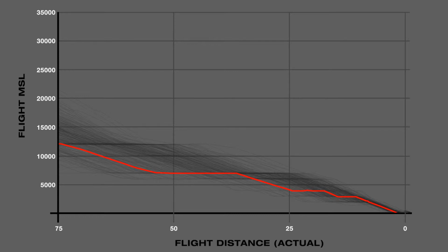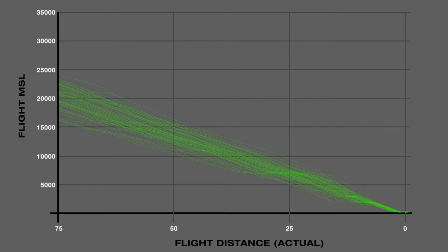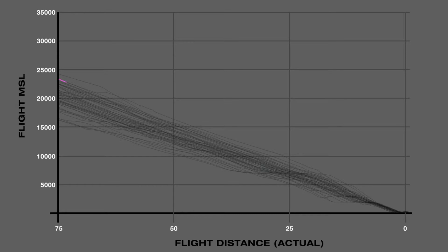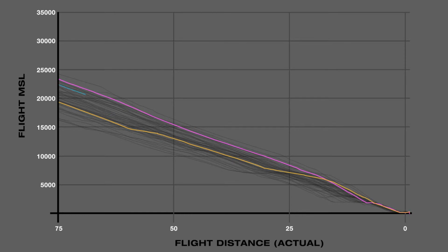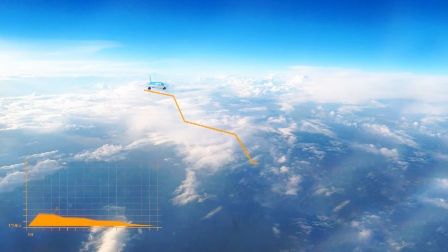By contrast, an optimized profile descent, or OPD, has built-in speed and altitude requirements at various points on the route. This information is programmed into the airplane's flight computers and allows them to essentially glide down to an airport on idle power and controllers don't have to issue instructions after clearing the plane to begin its descent. An OPD and optimized climb profile are much more efficient than traditional descents and climbs, and the key benefits that we're seeing today from our use of satellite-based procedures.